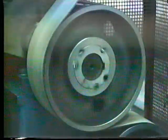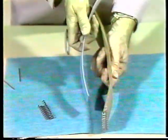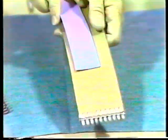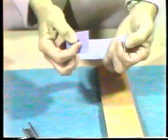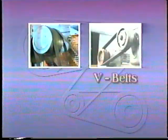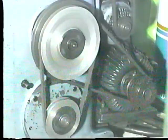Flat belts made of synthetics like nylons and polyesters are becoming more common. Since they can have a very thin cross-section and still be as strong as other flat belts, they can be used on very small pulleys at high speeds. However, since they are so small, they can't be joined by the clips or lacing used on standard belts. Instead, they must be bonded into endless belts by the manufacturer or with special equipment. V-belts are the most widely used drive in industry. They are easy to install, require little maintenance, and operate in a wide variety of environments without needing lubrication.